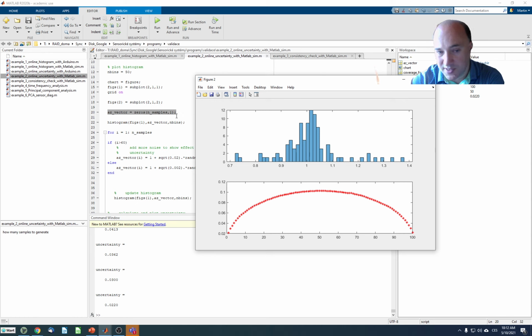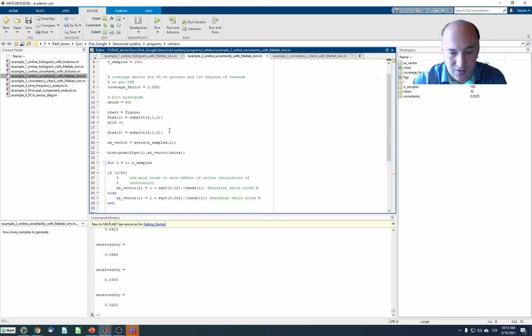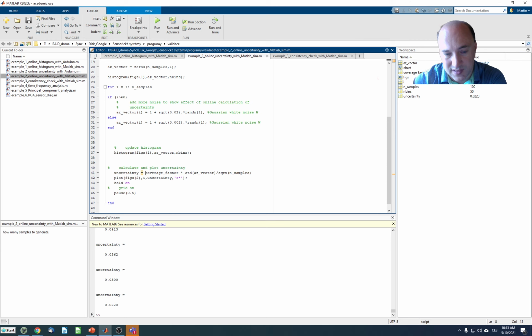the signal. I'm saying might because all this is based on statistics, and when we are calculating the uncertainty, we are playing with some probability distribution. So it's not 100% sure, but always you are selecting some confidence level. And you are also selecting this confidence level based on the number of samples. So if you don't know how to calculate uncertainty of measurements, then take a look in this guide to uncertainty of measurement document and see how this is done. It's not very complicated. The equation is basically here.